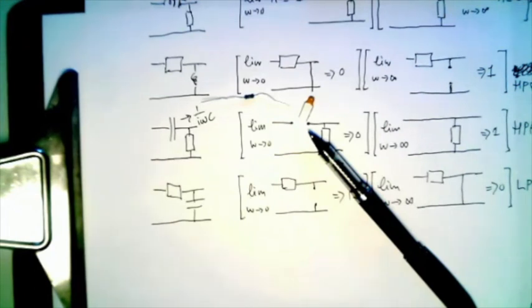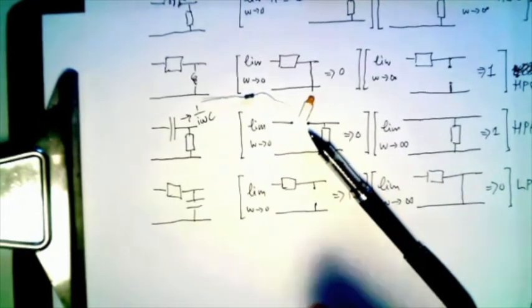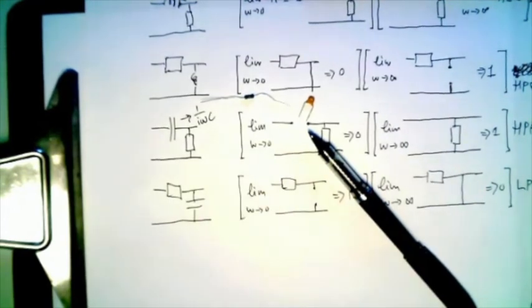If you have a conducting material that you stick in some kind of an ionic solvent, there is a potential difference that develops, and as a result of that potential difference, there's a capacitance that develops. So in your electrochemical setup, there's going to be capacitance, and then the ionic liquid is like a resistor, so that's an RC circuit. Just because you didn't put in a resistor and a capacitor doesn't mean that it doesn't behave like a resistor and a capacitor. So it's useful to be able to abstract it to resistor and capacitor circuits, and you'll be able to understand the world around you much better because you now have a solid understanding of how these things work.